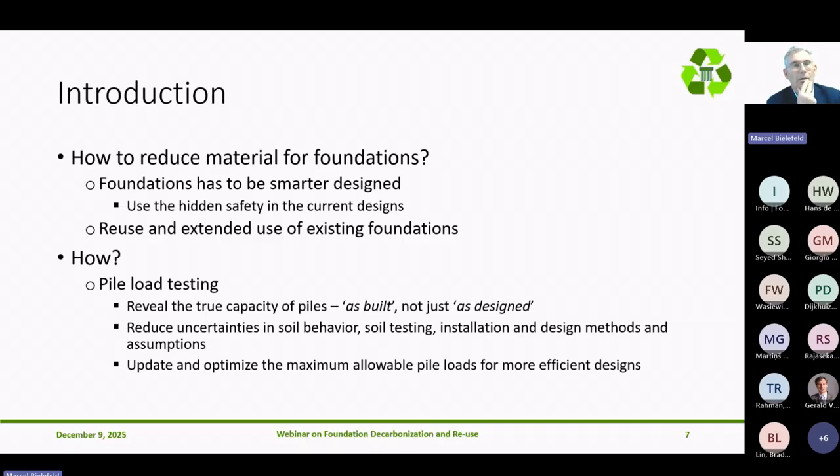And how can we design smarter foundations? Now, an important topic that can contribute to smarter design is the use of pile load test results, because that reveals the true capacity of the piles as they are built, not just as designed. That is the case for newly constructed foundations, as built instead of designed, but especially also for existing foundations.